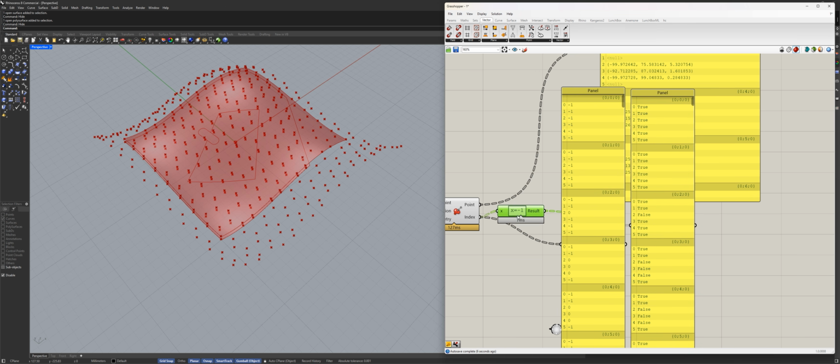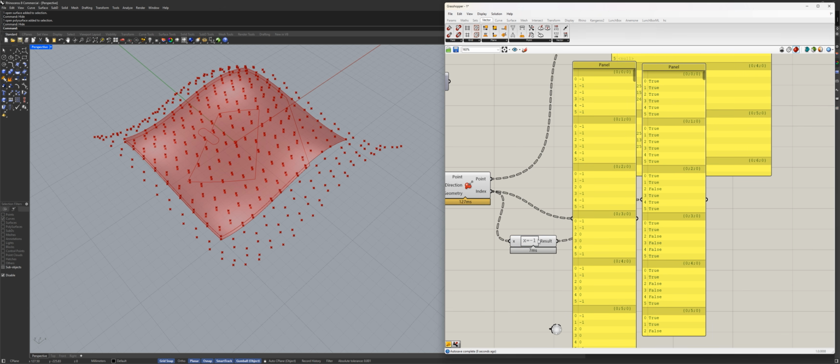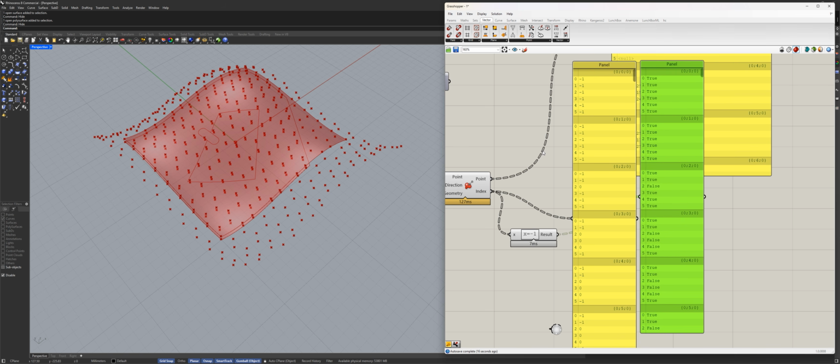The reason why this expression gives me booleans so easily is because these numbers are basically zeros and ones, and booleans are always absolute values. Grasshopper is smart enough to take this type of data without any conversion and give us the list of which is equal to -1 or not, the actual true and false.